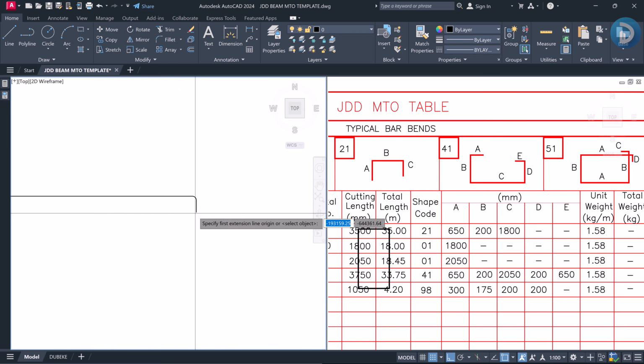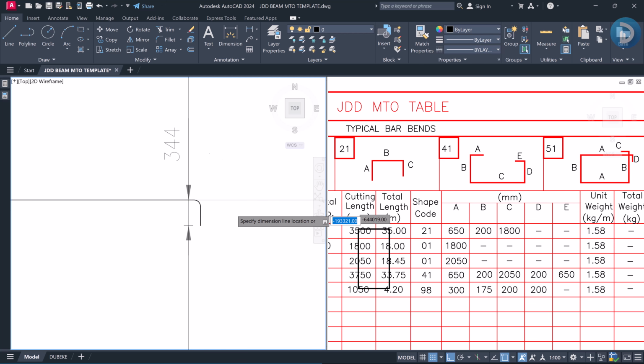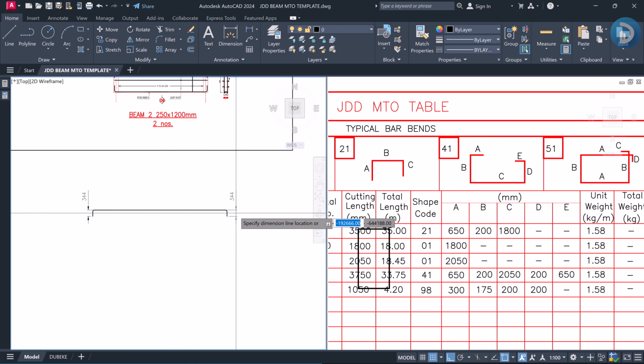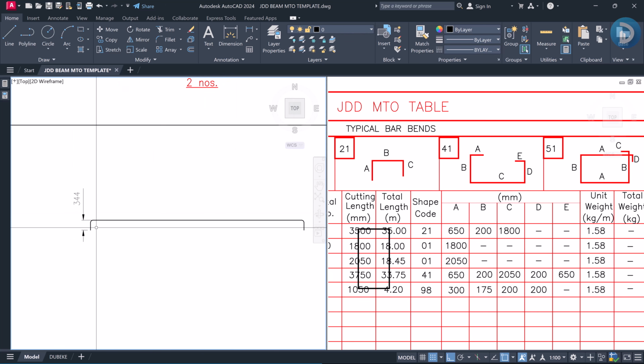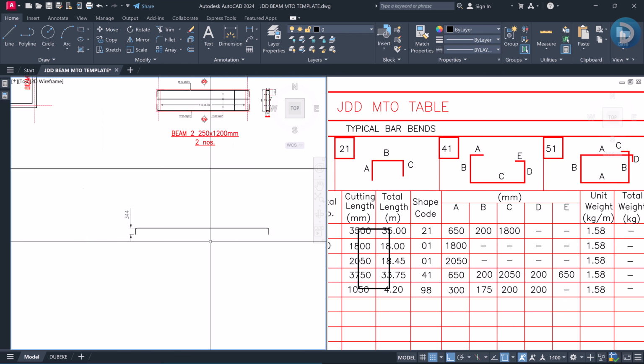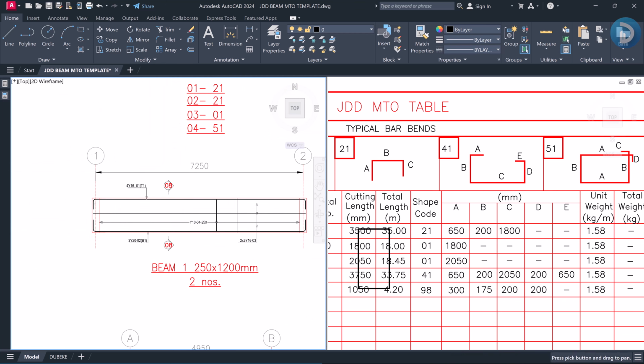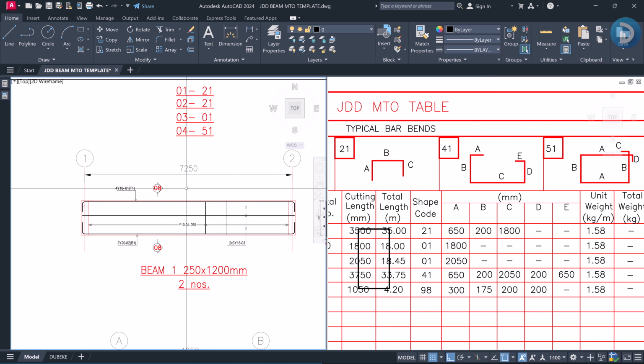We have the side C to be 44 millimeter as well. Now you know that this part of A and C is our development length, right? But for this main length here, the easiest way to get it is to look at the total length of your beam, right? We look at the total length of your beam, and you have to subtract your concrete cover.